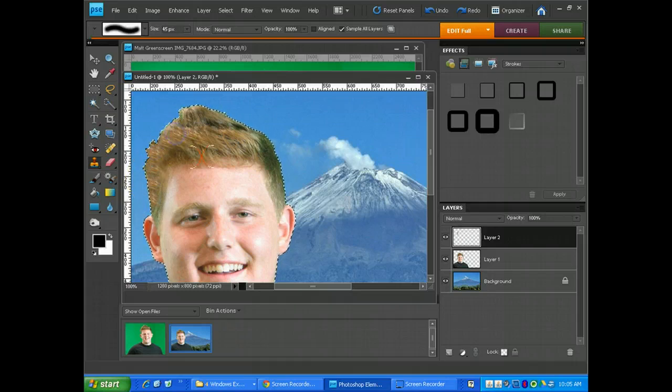Now this looks very artificial, starting to look a little bit too spiky. So here's the next little trick. I don't want to actually literally put the pixels there, I just want their color. So I'm going to change the mode of that color layer to color. And you'll notice what happens. Instead of painting pixels, it just paints color. And if I paint on the other side, I can kind of get the same effect there.